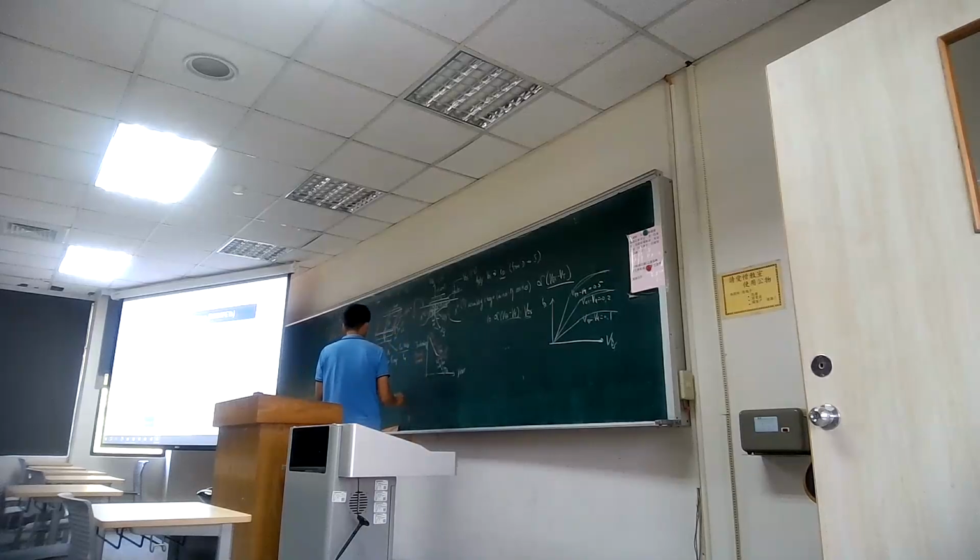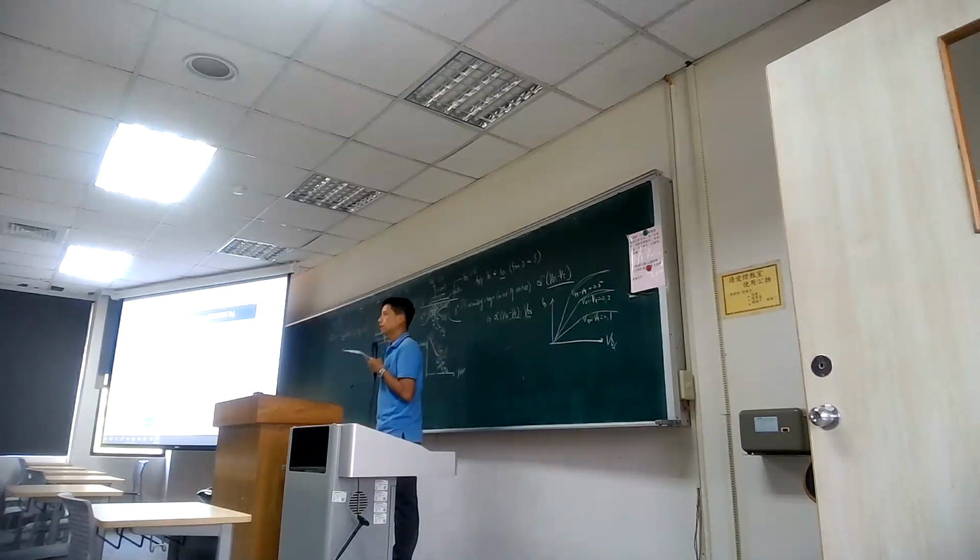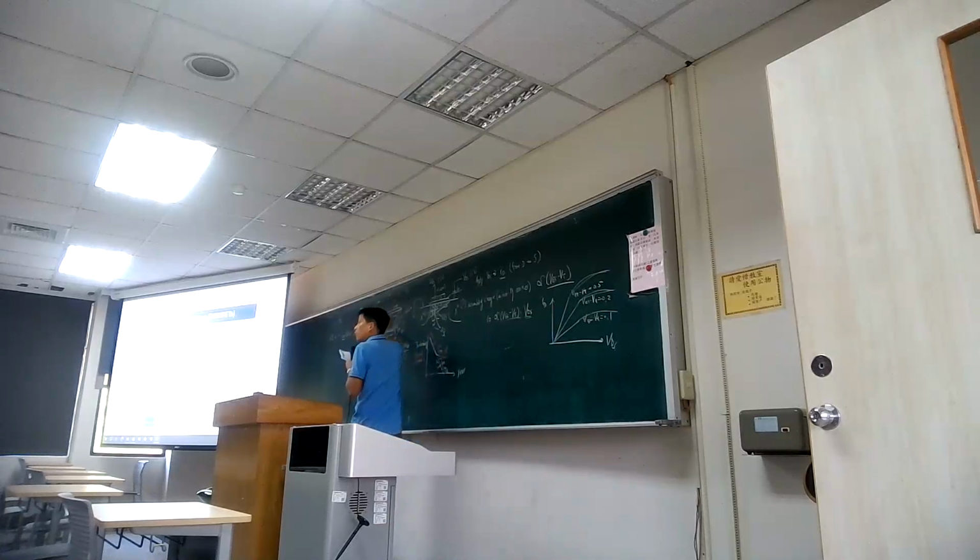And then for this strip, you can try to get some simplification. So epsilon over T oxide is like a unit capacitance without considering the unit area. So you can write this as C oxide W dx. The C oxide means epsilon oxide over T oxide.